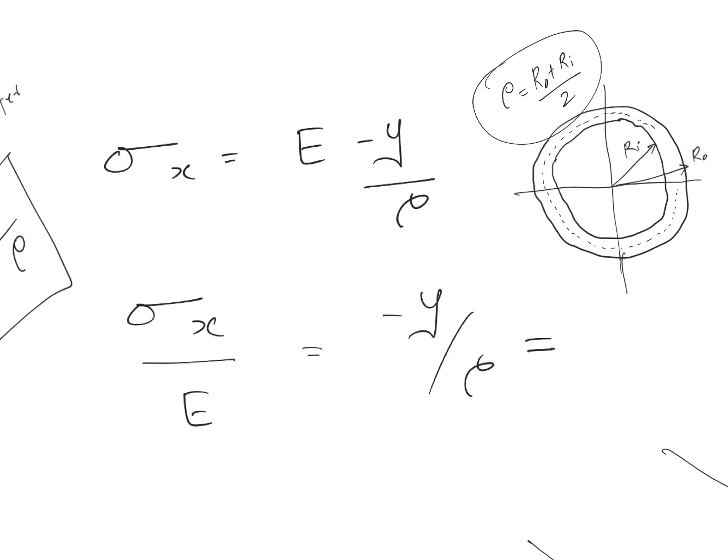There are exceptions, but for this problem where everything is homogeneous, the neutral axis passes through the center. Now I think we have all the tools in place. The rest is simply plugging in those values and evaluating the maximum stress that is acting in this bent beam, and where it will be acting, whether at the OD side or the ID side. Think about it.